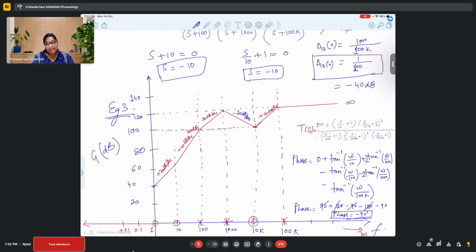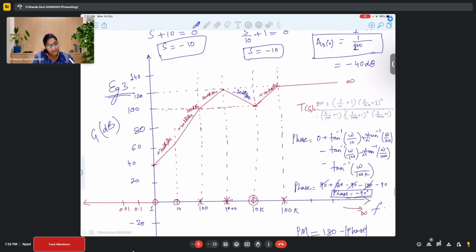So you are saying that suppose at the end I would have got a plus 20 dB per decade slope, and it would have been continuously increasing. That would be out of bound. If that happened, then basically the pole at 100k is not present.